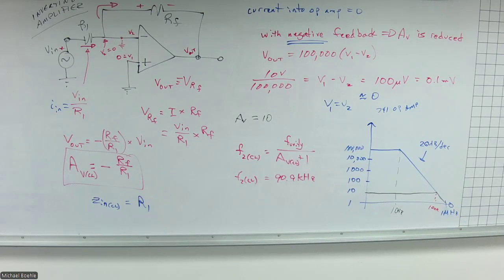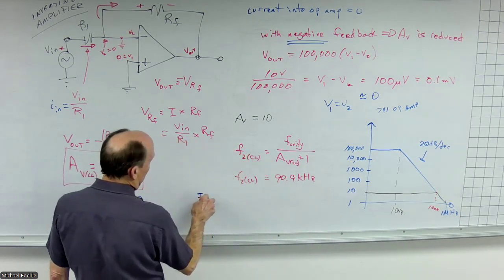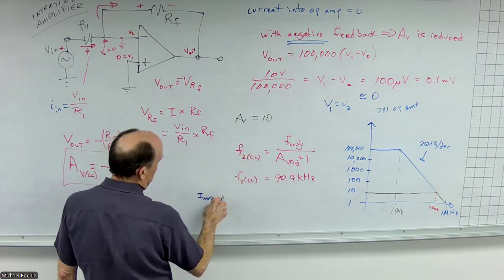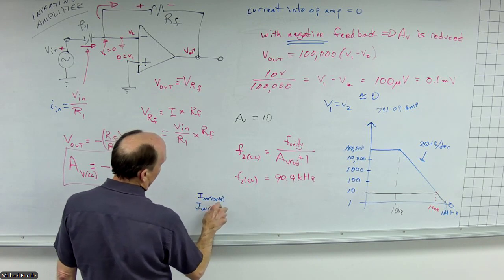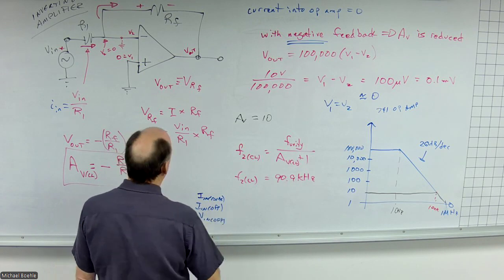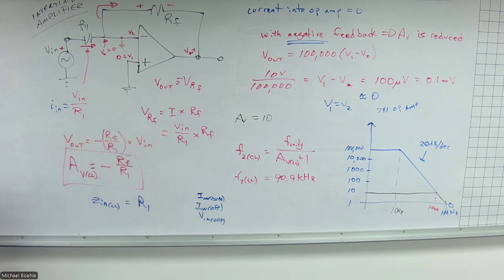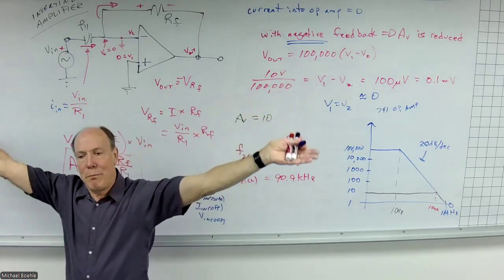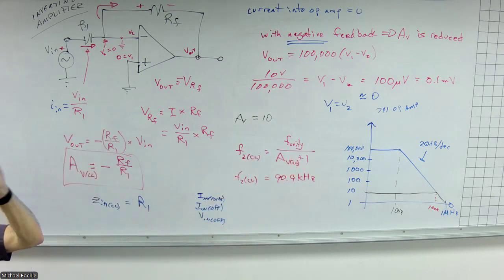Now, this is an op amp, all right? And so because this is an op amp, it has my input bias currents, input offset currents, and my input offset voltage. Well, imagine that's only a millivolt, right? We went through some numbers, it could be higher or lower. But with 1 millivolt times a gain of 100,000, boom, I'm going to end up saturated one way or another.